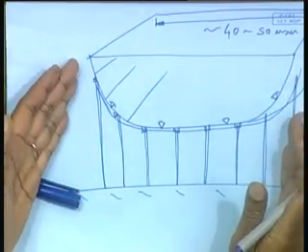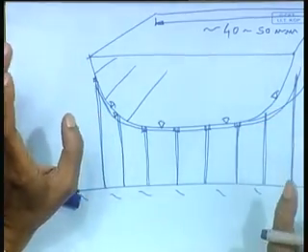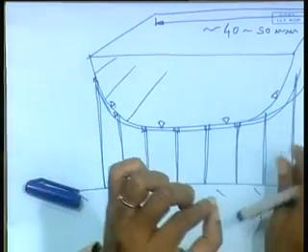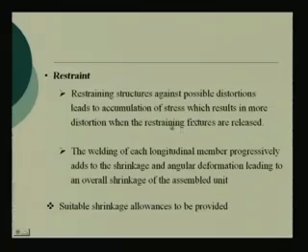When it was on the skid, welded, fine. The moment you have removed the tacks, it has just shrunk, because all those shrinkage forces were being restrained. The moment you leave it, it shrinks. That is what I tried to say here, that this restraining does not actually help much. Little bit it helps in the way of redistribution of stresses. Anyway, rest we will take a look at in the next class.